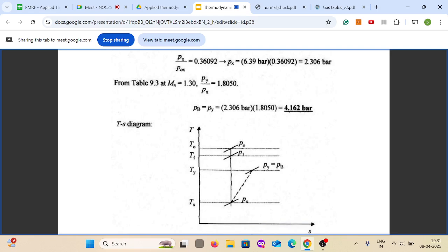We also calculated the velocities and the forces applied, and then we went to the normal shock and saw what is happening across the shock, and how the properties vary downstream and upstream. From the Mach number we went to the shock table and saw how to use it to estimate the properties, and it can also be found using the derived equations, which will be covered next week.